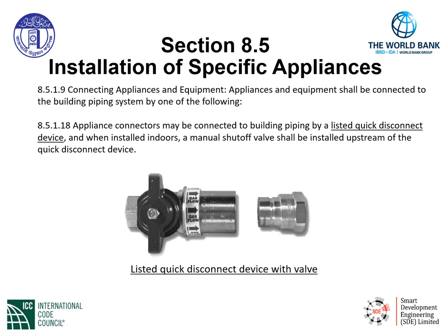The code section is specific because it indicates the requirement that appliance connectors may be connected to building piping by a listed quick disconnect device. And when installed indoors, a manual shutoff valve shall be installed upstream of the quick disconnect device. Now, the picture down here shows a valve that is actually manufactured into this quick disconnect device. So you can buy these accordingly.